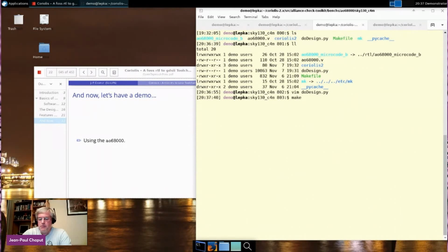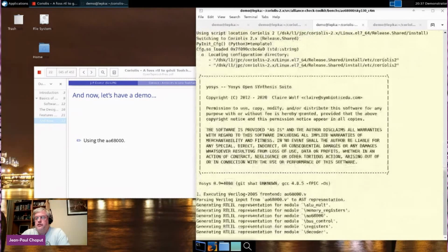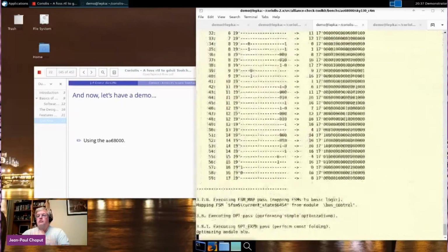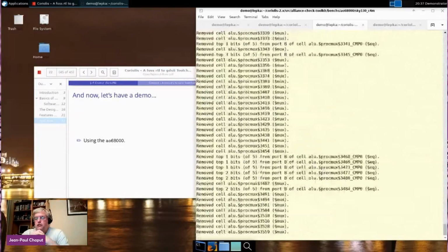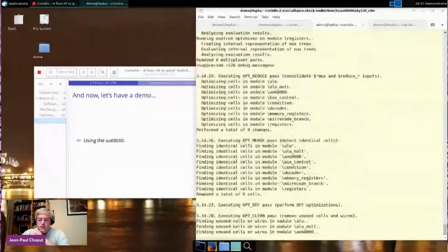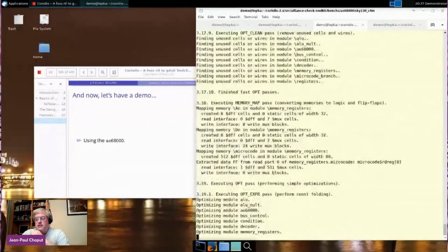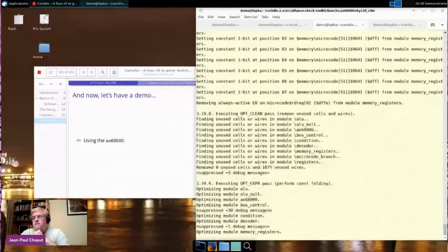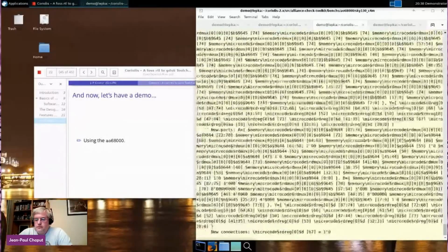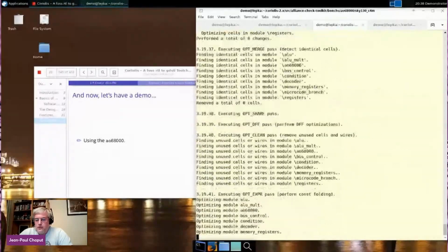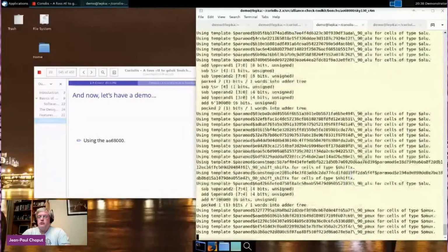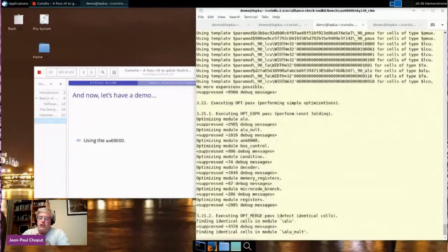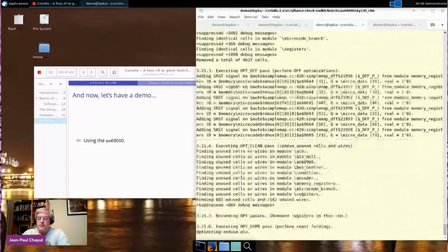So first step is to perform the synthesis. So make vst. We just call Yosys. People knowing Yosys will recognize its output. We just take a little bit of time to perform that. It will take about 5 minutes, not the whole flow, not just Yosys.